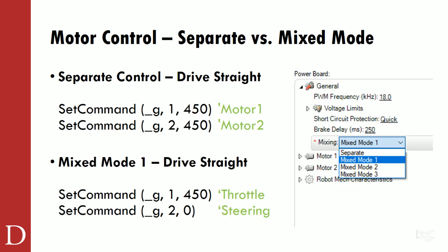All right, now let's get into what we're going to actually do inside of MicroBasic. So this is going to be the command that you're going to want to know right now. This set command is what you're going to need for actually turning the motors on your AGV. It doesn't matter that we're only doing it in a simulated environment. It's the exact same command for when we're doing it with the actual Minibot.